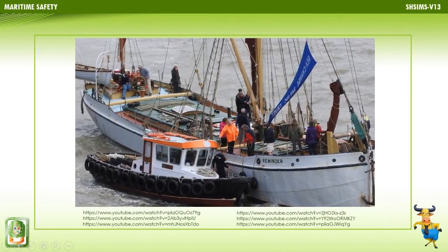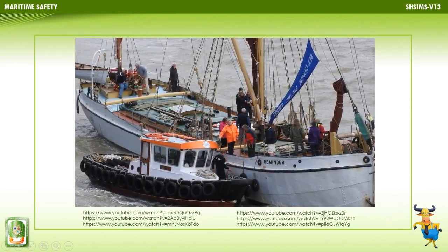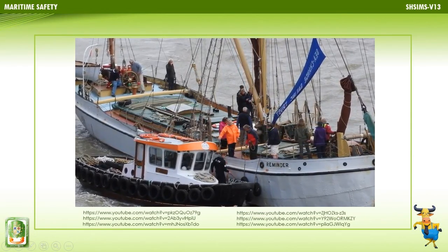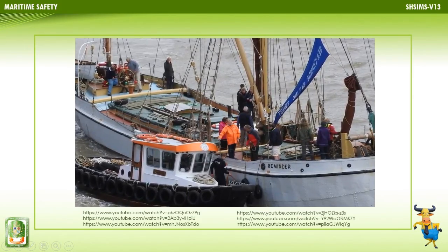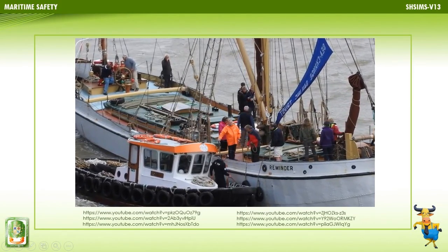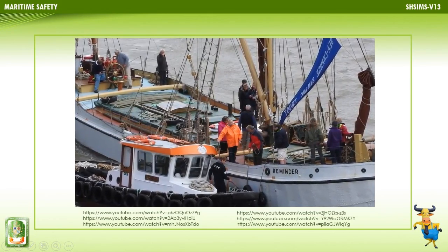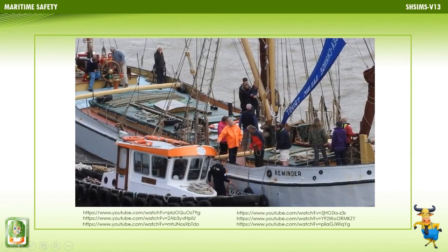put over, at 6 knots the vessel will have traveled 9 meters. At 12 knots the vessel will have traveled 18 meters. Initiating an immediate turn to avoid propeller strike is not only irrelevant for most CRVs, but a potential hazard, risking injury to other crew or even a second man overboard.